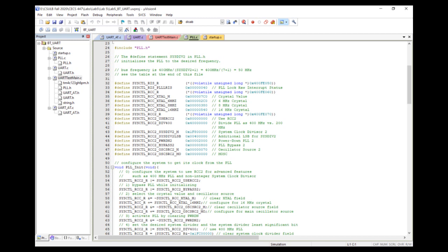The purpose of this lab was to set up a HC05 Bluetooth module with a TM4C and communicate via a smartphone serial terminal. The PLL.C file utilizes the onboard crystal to enable a clock and set the bus frequency. This module is required to use timers effectively in the grand scheme of the project. The bus frequency is set to 50 MHz.